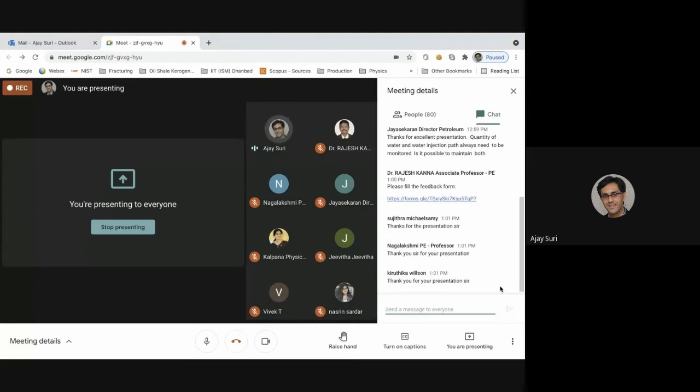That is one thing. But what it can help with is between the different layers. Sometimes if you are injecting in multiple layers, we may be sweeping one layer, or we may not be sweeping one layer, like I showed you in one case study, because of a fracture growing in one layer and not growing in another layer. So it can track that and tell you, oh, you are fracturing one layer more than the other, so you need to be careful because the model is telling you. Or else you will have to do a production log or injection profile to be sure whether it is going into both layers. But the model can at least give you a warning first.